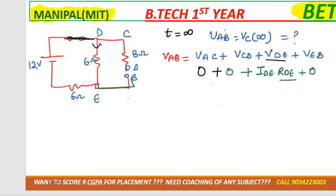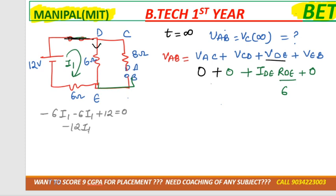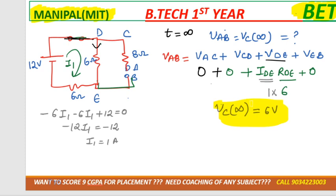Now RDE means the resistance across D to E, that is 6 ohm. IDE is the current flowing across the 6 ohm, and that we can easily get by mesh analysis. So it would be minus 6I1 plus 12 is equal to 0. So minus 12I1 is equal to minus 12. I1 would be equal to 1 ampere. So IDE means 1 ampere. So ultimately we'll get VC of infinity as 6 volt. Finally, our step number 2 is also completed.